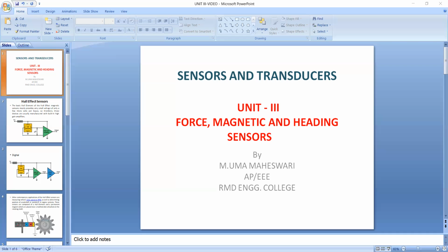This movement of charge carriers is a result of the magnetic force they experience passing through the semiconductor material. As these electrons and holes move sidewards, a potential difference is produced between the two sides of the semiconductor material by the buildup of these charge carriers.